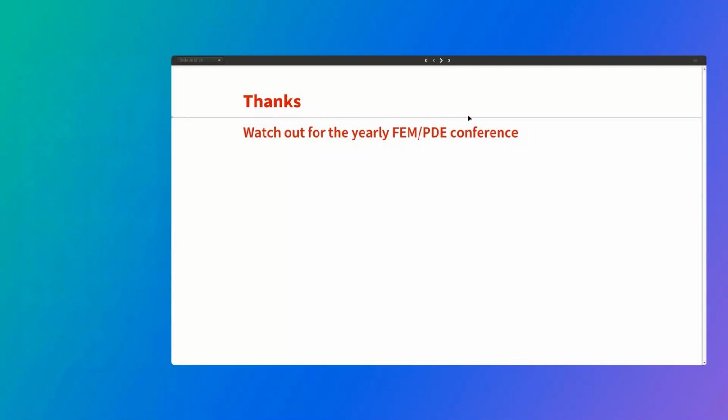So next question: any suggestion on how to become familiar with functions and tools for mesh creation? When I see the code in examples, it makes sense, but it would be good to develop an intuitive understanding for new problems. What can I recommend for that? Probably different people would give you a different answer, depending on which team you'd ask. In 2D, I think you're pretty well set with the standard functions built into the Wolfram Language, with maybe the exception of when you generate multi-material regions. For those, I'd suggest to use ElementMesh.